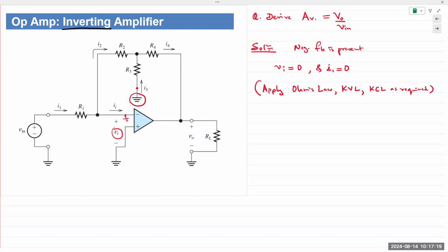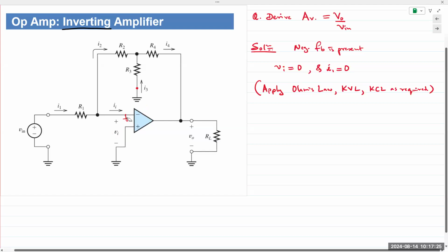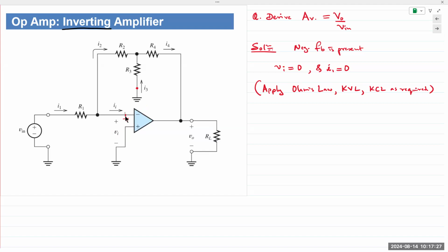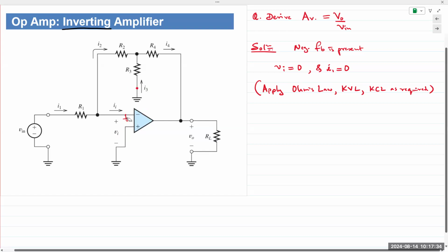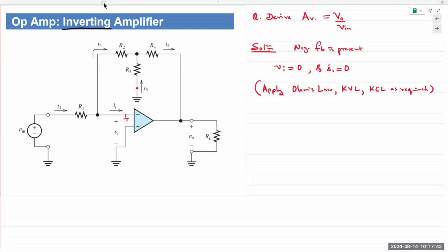So ground in that case would be like a floating ground that is simply just the negative end of that battery. Does that make sense? So in this case, we see the bottom end of R3 is connected to that common terminal or ground, which basically are all of these. All of these are also connected there.